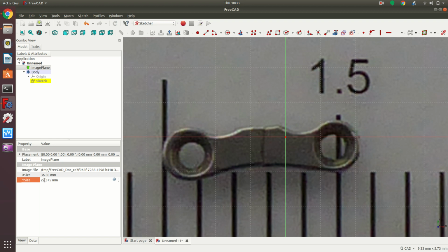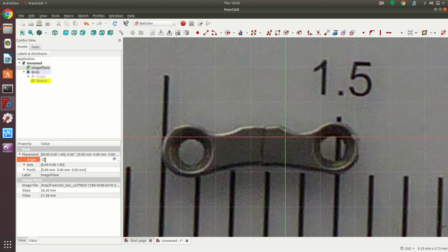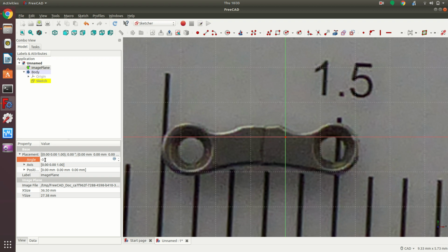What we also notice is we're slightly tilted to the left. So we got to turn this thing clockwise. So we go to Placement, Angle, and give it 1 degree. Oh, we got to go negative. So minus 2.5, minus 3. Perfect. Look, the lines here are just so.